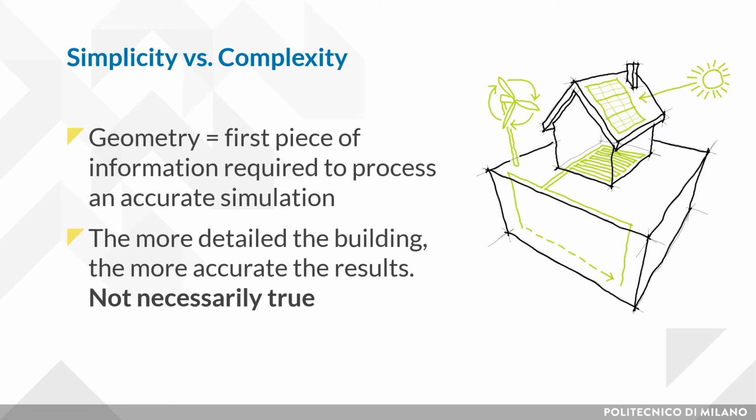From an architectural perspective, models are typically outfitted with every detail of the building's design, with the goal of producing realistic orthographic views and renderings. There are some details in your building that will have little or no impact on the energy performance, and in fact, they will increase runtime and can be significant sources of error. It's best, therefore, to leave them out.